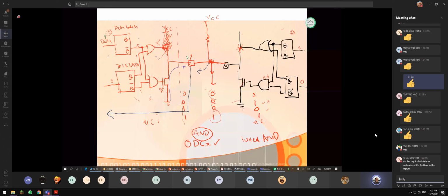Starting from 4 o'clock, we try to use the ESP32 on the spot. Please be ready with your ESP32. The most important thing is the cable that connects to your ESP32. Make sure that it's a data cable. Do you still remember the USB cable? It's not a USB type C. Please check, and make sure the cable is a data cable, not a power cable. If it's a power cable, your ESP32 won't work.